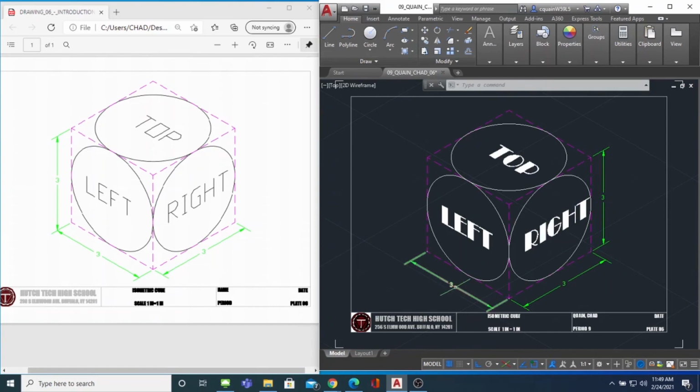Other times it doesn't. I don't know if it's something with the version of AutoCAD that we're currently using or what it is. But normally if I do dim style and then I change something and I go set current, it automatically updates everything. But if you ever run into that problem where it doesn't update for you, now you know a little trick using the properties, okay?